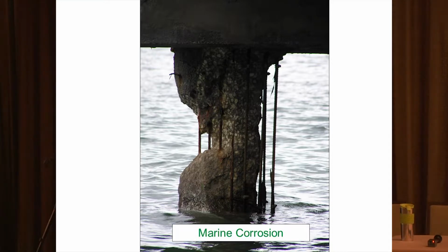For the last 15 years, we've been using these distributed anodes typically in a pile encapsulation or pile jacket type system. Here, we tie the anodes to the reinforcing steel, and then we encapsulate the anodes inside concrete or grout.